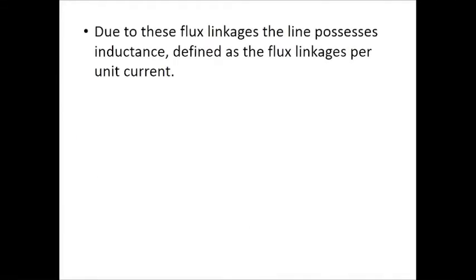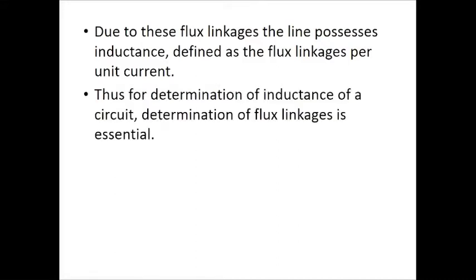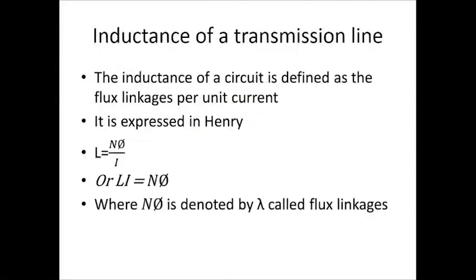Due to these flux linkages, the line possesses inductance, defined as the flux linkages per unit current. Thus, for determination of inductance of a circuit, determination of flux linkages is essential. So, inductance of a transmission line. The inductance of a circuit is defined as the flux linkages per unit current. It is expressed in Henry.